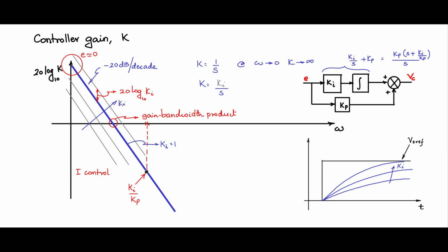The plus 20 dB per decade and the minus 20 dB per decade will cancel and flatten out in this fashion. So what have I achieved with this? If I had not put this Kp, the gain would have fallen down like that. But now I am gaining extra gain as frequency changes. So I am improving the high frequency gain in this fashion.